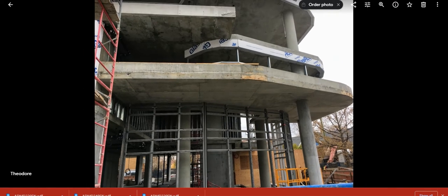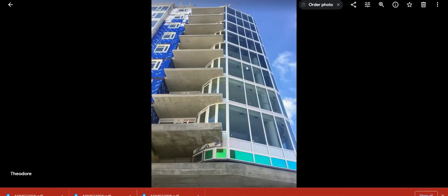I'm not sure what the limitations are to the height of the window wall systems. I'd have to dig into that, but maybe this floor-to-floor height was too much for that system. So here they are putting in a curtain wall frame system, which can get a much greater span height. And there's just an image of that window wall system going in afterwards. Okay, so anyways, back to our detail here.